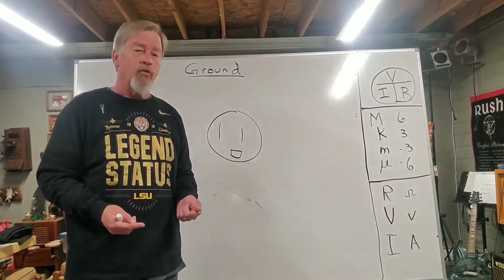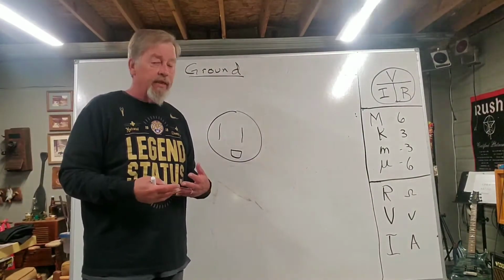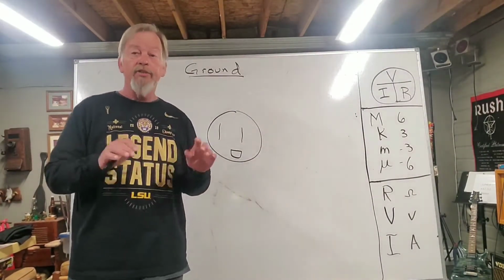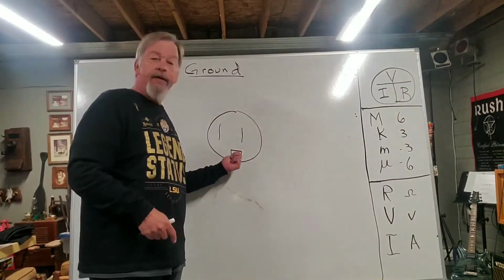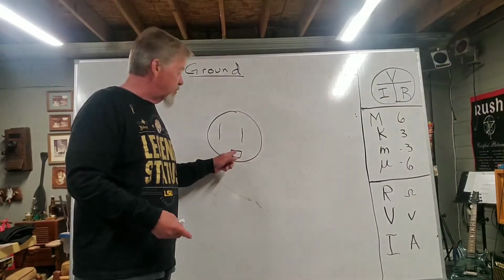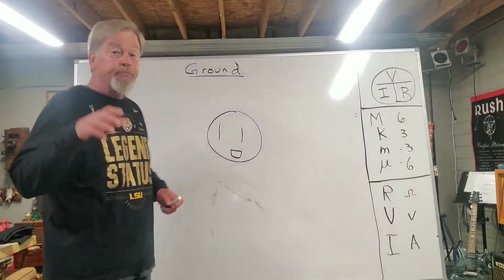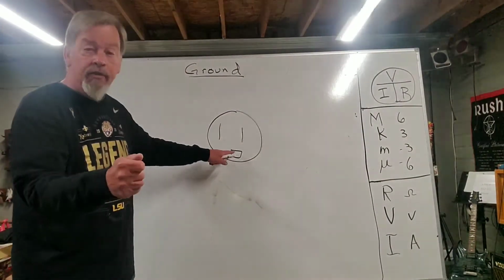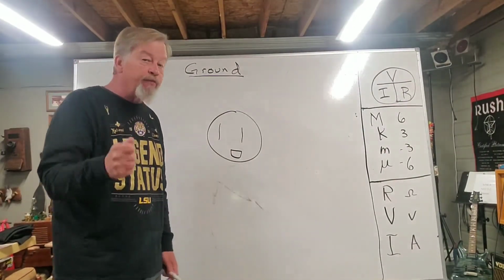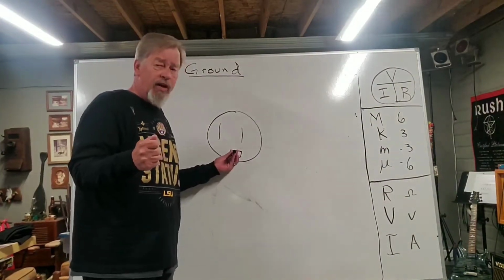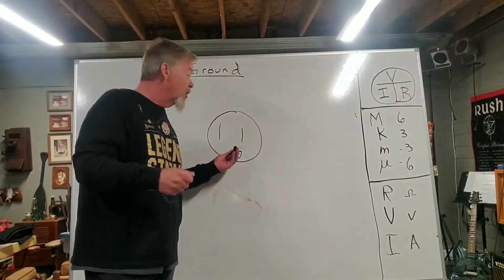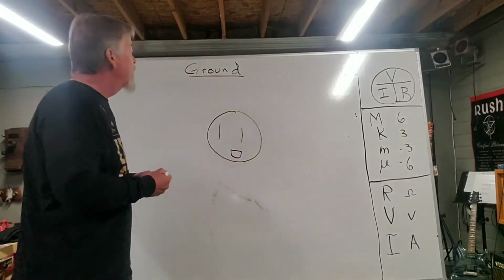So ground was introduced for consumer safety. What that does is everything that a consumer can touch that's conductive is going to be connected to this point. The reason that's important is because if this point is ground, what you're standing on, and you grab something that is at ground potential, there's zero difference in potential, therefore you're not going to get shocked. And if there is current on that neutral, it'll actually throw a breaker. So ground was introduced in 71 simply for consumer safety.